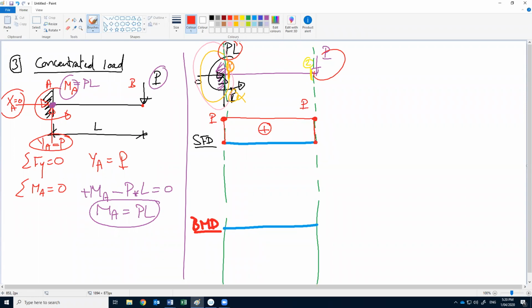I will draw it here again. We are here at 1, and the tail is above the datum. So our moment will be here above the datum, and the value is B multiplied by L. Okay, the moment at 2. We can calculate from the left or from the right. It is easier to do from the right.